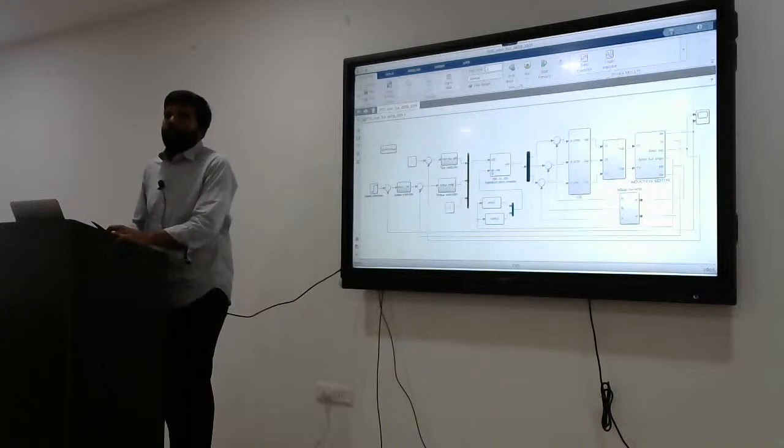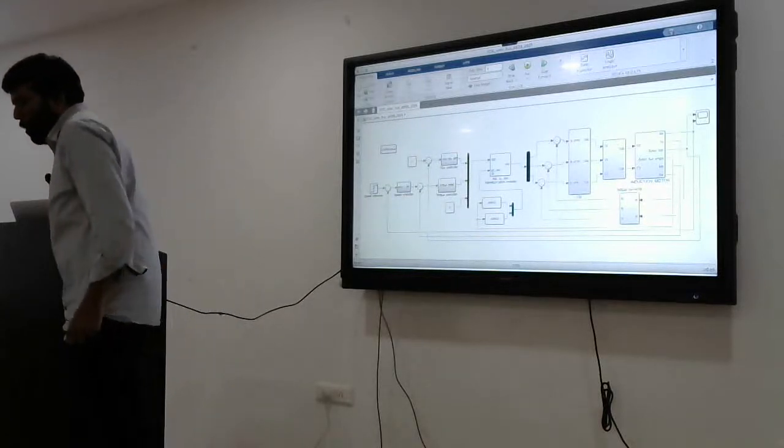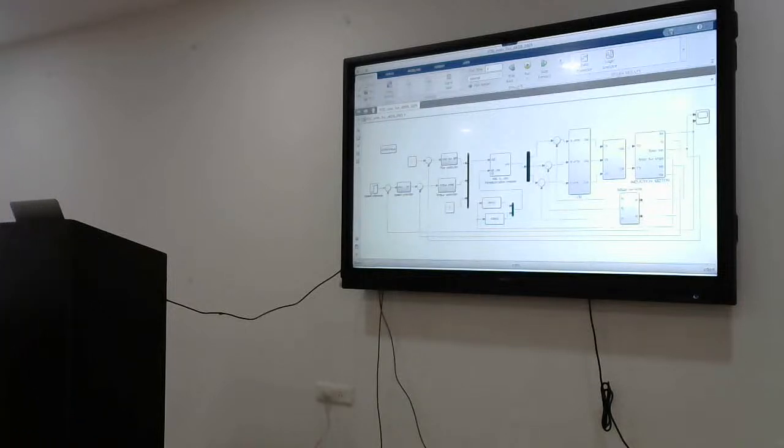Here, what is the problem? Before going on to discuss another advanced speed control method, I want to ask one important question. What is the main drawback of the field orientation method? It requires transformations; 3-phase to 2-phase is required. Orientation is also very challenging. These two are very difficult in practice.